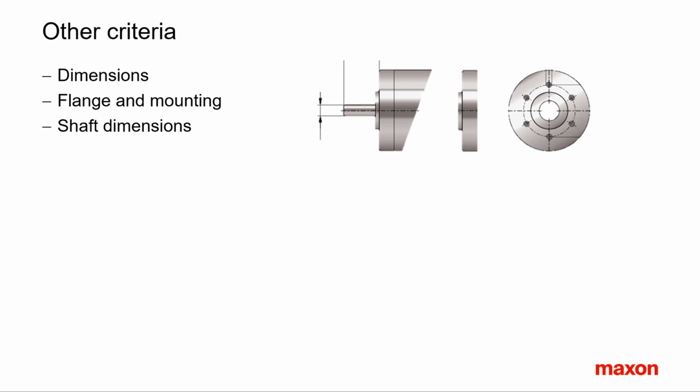In addition to these considerations about torque and speed, there are other questions related to the selection of motor size that need to be addressed. The first one being the mechanical interface. What is the maximum diameter and length that is possible? How is the motor going to be fixed? Are there any restrictions concerning the size of mounting flange? And how about the shaft diameter and length?